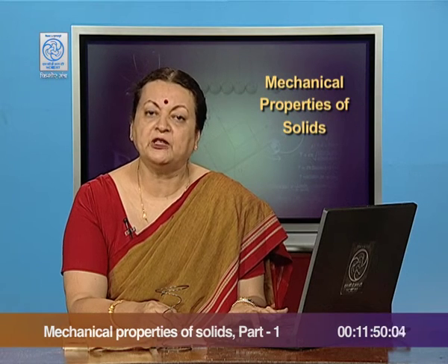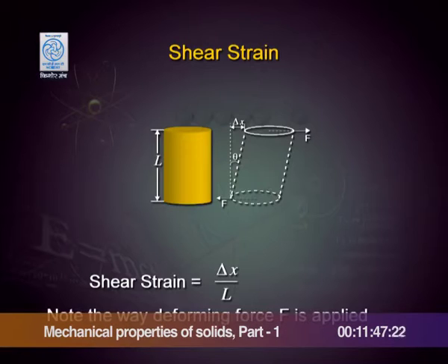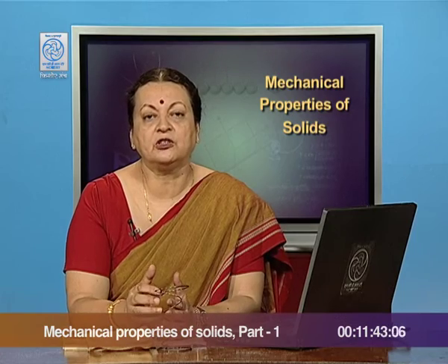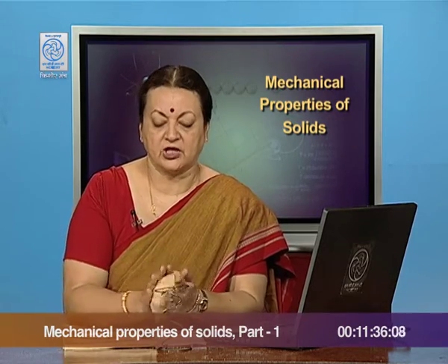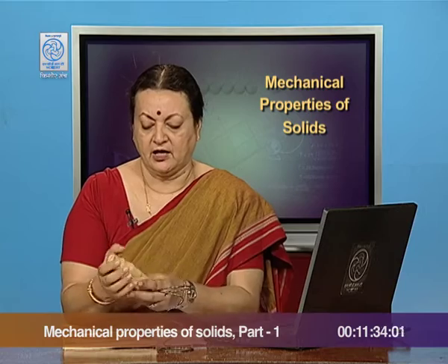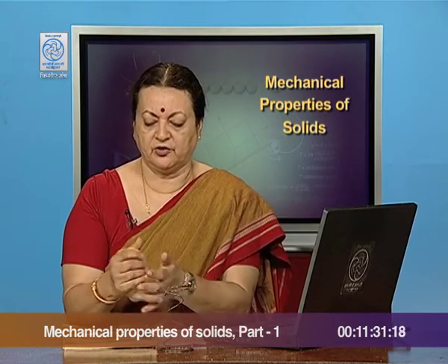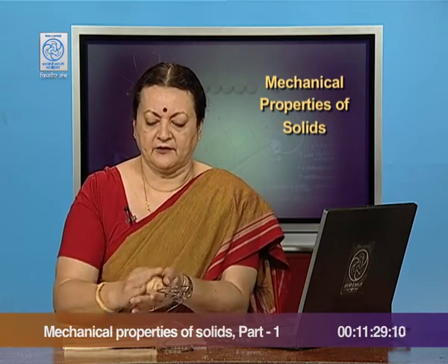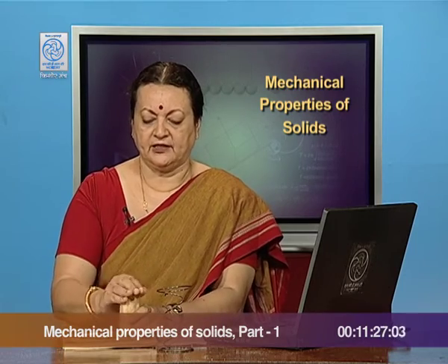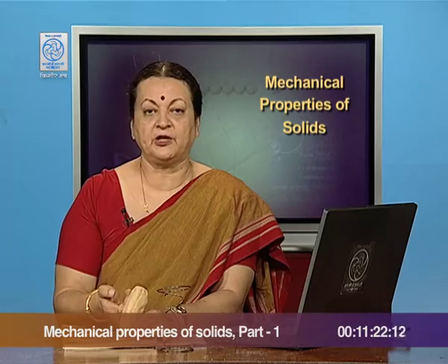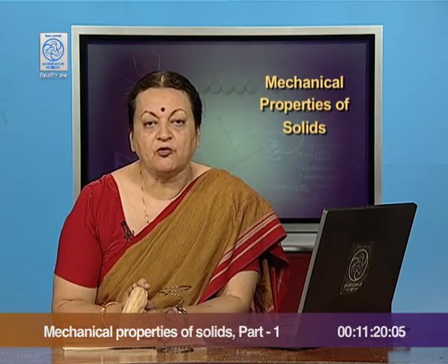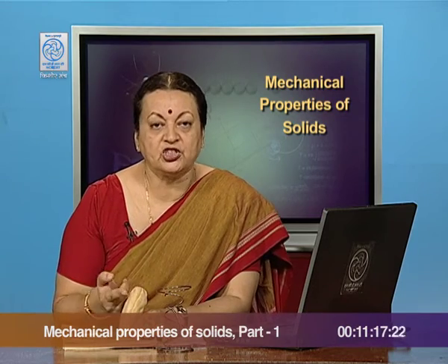Likewise, what would be the meaning of shear strain? Shear is a word used to talk about the deformation in the shape of the body. This will obviously depend upon how you apply the force. Supposing I get back to my cylindrical condition for this dough, and if I hold it up like this and apply a force tangential to it, the change in shape here is responsible for the shear value, the shear strain.